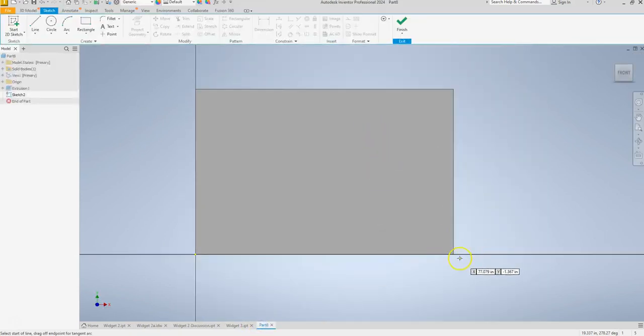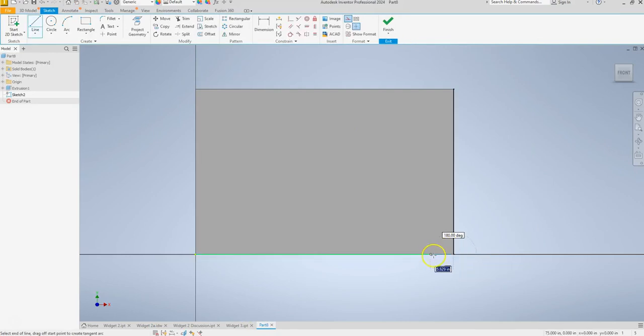So let's go ahead and start in our lower right hand corner with our line on, as well as our construct tool, and we are going to come in 25 because we know that each end part is 25 and the middle is 25 because we know our length is 75, so 25 plus 25 plus 25 is 75. Click enter, and then we can click escape,